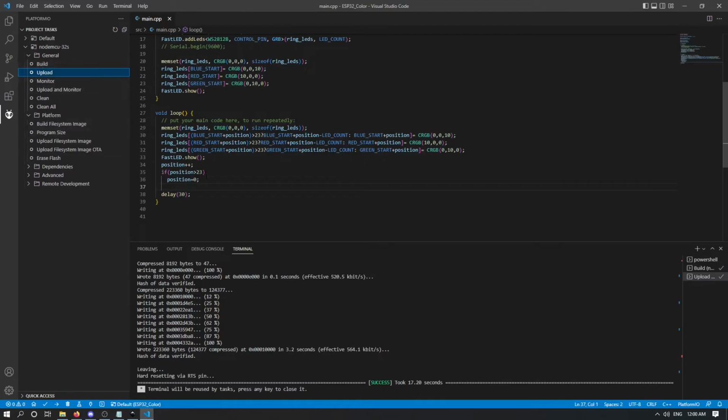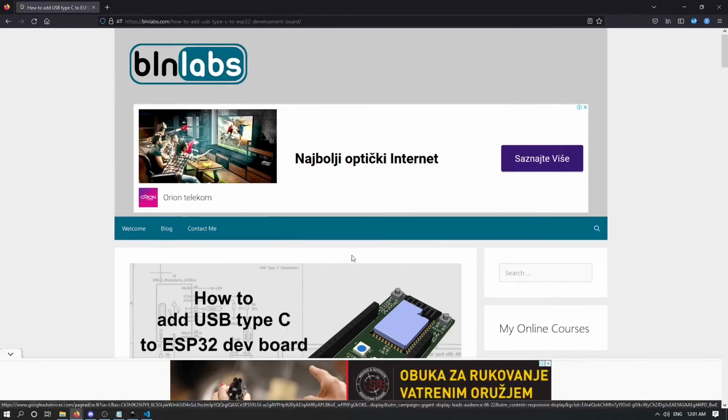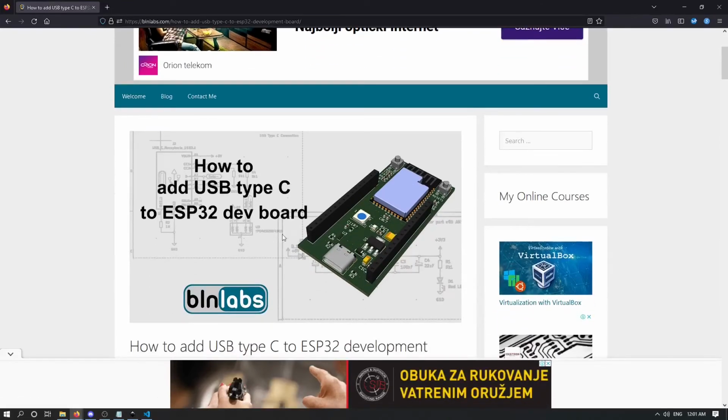And I think that is the power of these fully addressable RGBs. Because of that reason, when I designed my custom ESP32 development board, I actually used this fully addressable RGB as its status indicator here. I didn't see that someone uses something like this, but the way that I can control and select each color by only one pin, I think this is a very nice implementation here with these ICs.